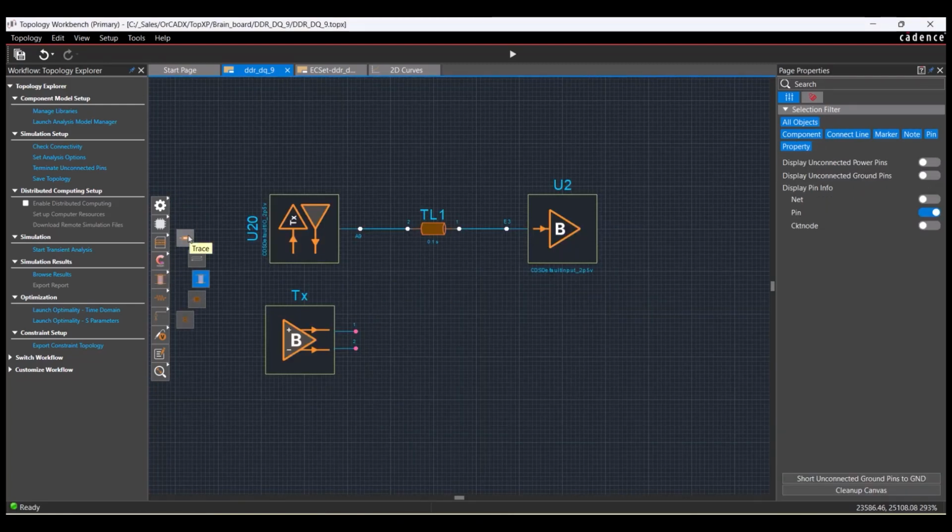You can add routed interconnects, cables, vias, ideal transmission lines, coupled transmission lines into the design. You can also add discrete components like resistors, inductors, capacitors, diodes, voltages. You have a lot of capabilities that you can add to the design. This allows you to add voltage probe markers. So if you want to probe the interconnect someplace other than the driver and receiver, you can do that as well. You can even add notes to the design canvas because sometimes this becomes something you need to document.